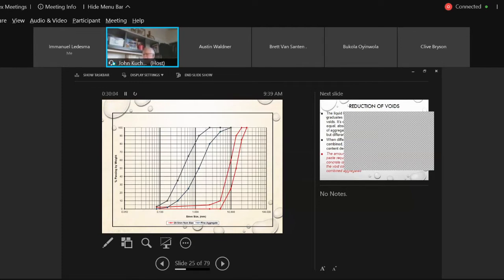Okay, here. So when you're plotting aggregate gradations, I know in previous labs a lot of students would plot one gradation per grain size distribution sheet. Here you can plot 2, 3, 4 gradations. You're going to see when we're talking about asphalt, I plot sometimes 5 on one graph. I can see it all in one shot. I don't have to flip through pages. Here I'm plotting the coarse, and here I'm plotting the fine. And then when I decide to plot it, I'm going to have another legend here, maybe it'll be dashed or dotted, to show the actual grading limit. So these are the limits, okay?